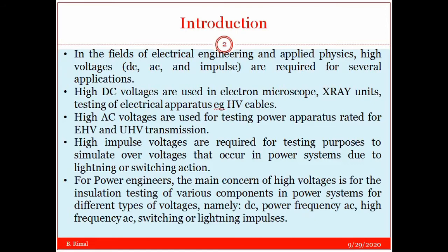Similarly, for power engineers, the main concern of high voltage is the installation testing of various components in the power system network. This test might be a high voltage DC test, power frequency AC test, high frequency AC test, or switching or lightning impulse test.